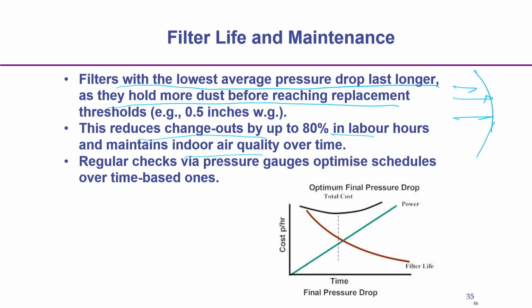Now, you can see the filter life reduces, because a higher pressure drop means higher particle deposition, and a higher pressure drop also means the filter can get damaged. So, to enhance the filter life, we should maintain the lower pressure drop.